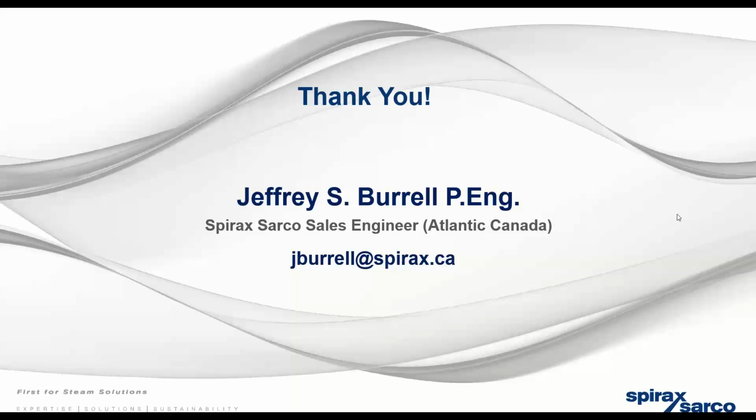Yep, agreed. I have another question here about high pressure. What is a good remedy for high pressure converters that are feeding variable volume perimeter systems? How can you regulate steam to reduce flooding and water hammer? On these, in my opinion, the way to reduce water hammer and flooding is to ensure proper drainage.